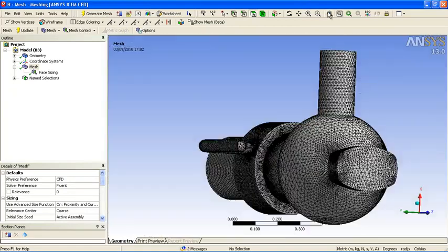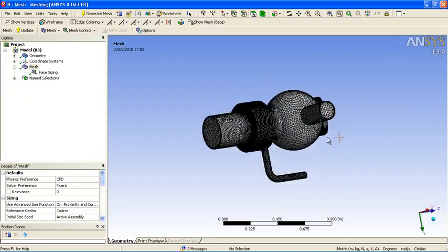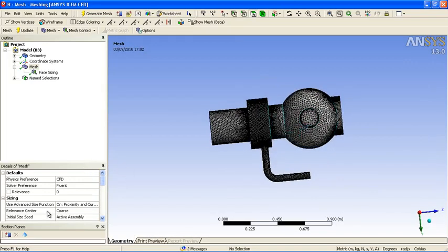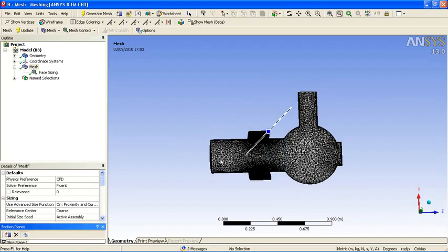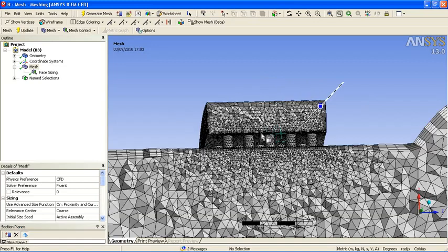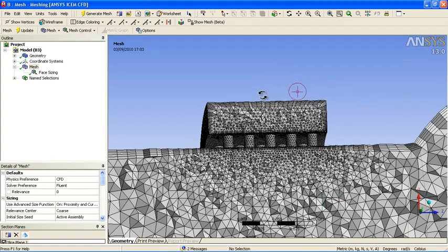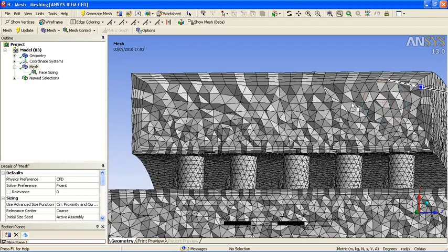and there are two inlets to this model. Here's the first inlet, and finally the inflation on the second inlet. So you can see that it generates a very high quality tetrahedral and prismatic inflated model with very minimal user input. If we take a slice plane, you can also see how the inflation layer varies in height depending on local element size and geometry features. So you can see the smaller offset where you have the smaller tetrahedrals.